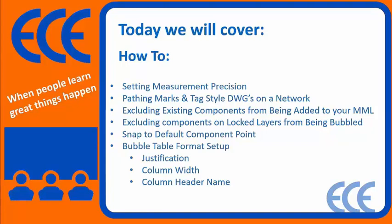Snapping to default component. All components in CADWorx have an insertion point. So when you put a bubble on a component, it'll go to the midpoint of the pipe or the midpoint of a valve or whatever the insertion point is. We'll look at how to turn that snap default on and off so you can place bubbles where needed.